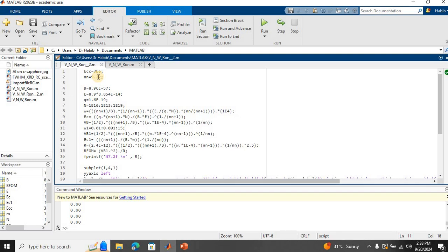Then N over here in this MATLAB code is a material specific constant used in the modeling of breakdown voltage or depletion characteristics in gallium nitride. This parameter is related to the empirical fitting or analytical model used for gallium nitride PIN diodes.